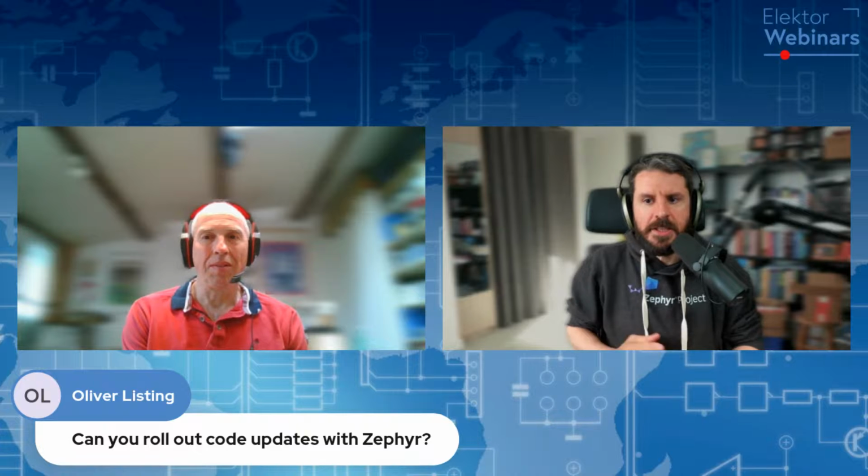to kick in, then it would bootstrap the Zephyr application. But what that means is that you would have two partitions in your flash, and by default MCUboot would know which one contains your current version of the application.